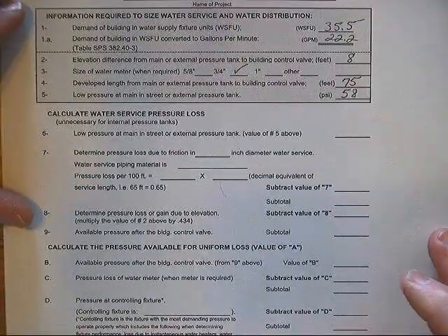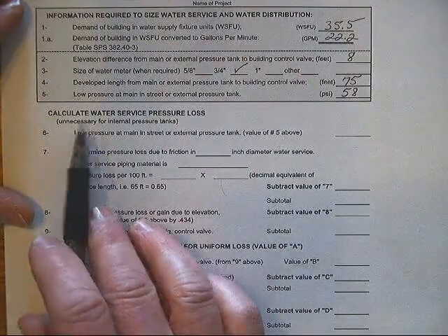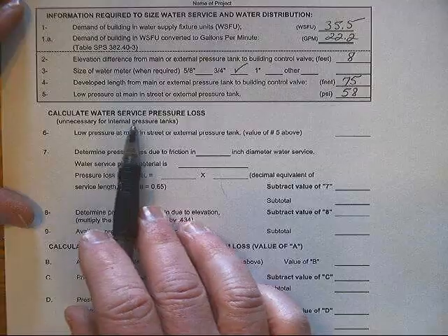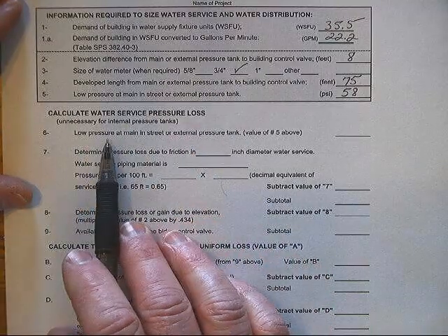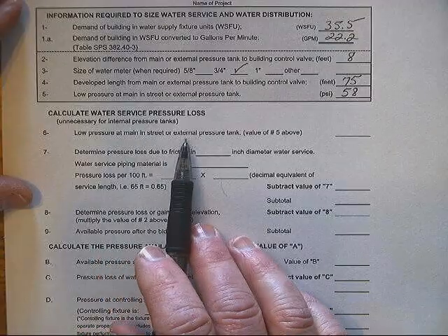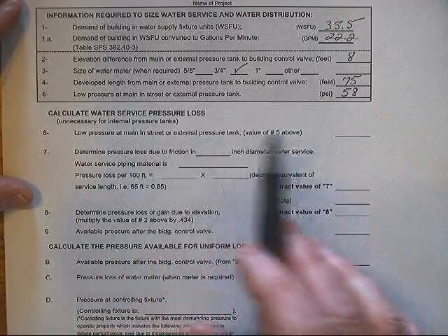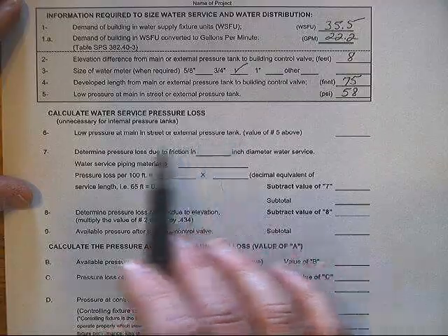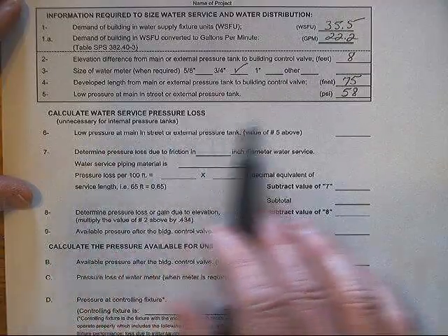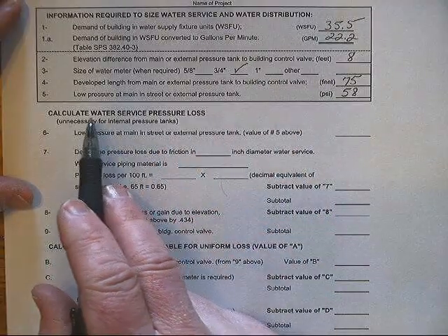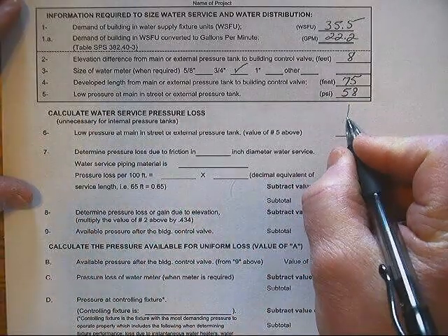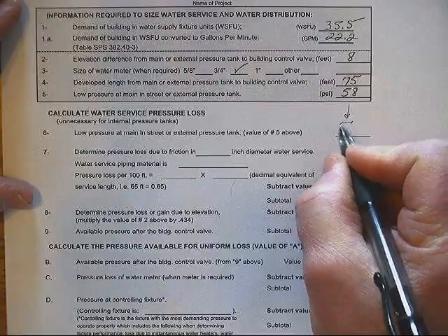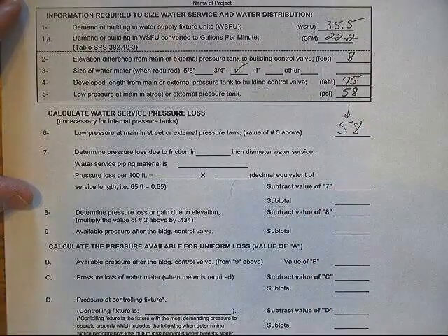Alright, the first step of the calc sheet asks us to calculate the water service pressure loss. Step number 6 says low pressure at the main in the street or an external pressure tank, which we do not have. We do have low pressure in the main, and that's actually from step number 5 right above us. So we'll just take that number and drop it on this line, and we'll start out with 58